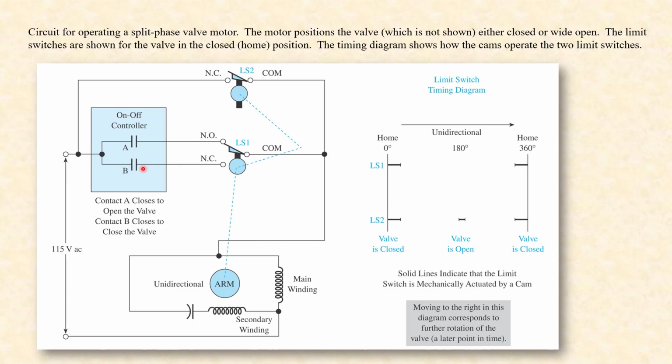Well, we're not telling it to close, we're telling it to open. So there's nothing here. This is a dead end. So does the motor stop as soon as this comes off? Because that's breaking the supply. No, because as soon as this one comes off, this one comes off. And when this one comes off, now this falls down and makes a connection, and that power comes this way.